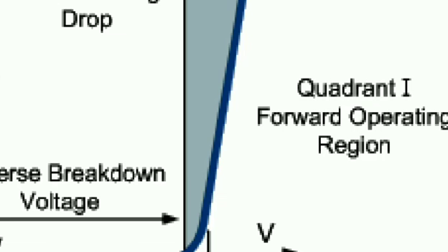See here, when we connect the positive terminal of a battery to the p-type semiconductor and the negative terminal to the n-type semiconductor, what will happen? We are connecting the positive terminal to the p-type semiconductor, and what do we have in the p-type semiconductor? Holes. So there will be repulsion. The positive terminal of the battery will repel the holes of the p-type semiconductor and they will get pushed towards the junction and enter the n-type semiconductor.